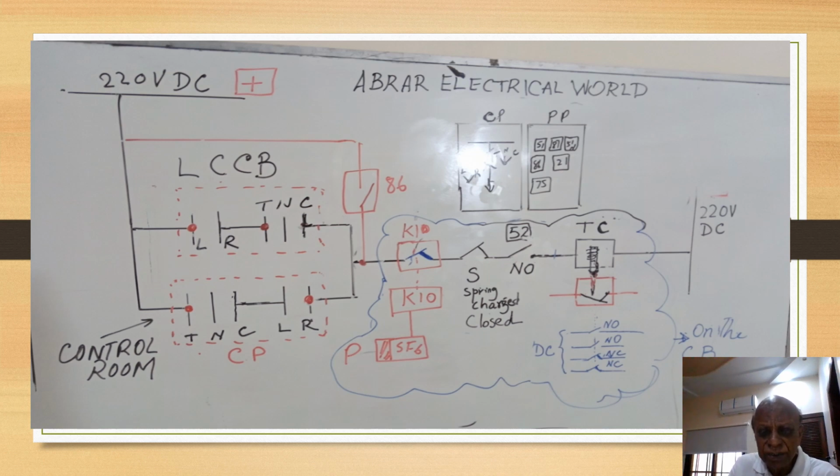So this is the gas density meter or gas pressure relay. It is also known as the gas density meter. In some drawings you will see gas density meter, and in some you will see gas pressure relay. This will actuate when the pressure is okay. It will be energized, and when the pressure is okay, the contact is closed. If this is open here, then this will work when energized. It depends how you draw the logic. Anyway, it is an in-between auxiliary contact which has heavy contacts, and one of them is used here. When the gas pressure is full, then this is on.